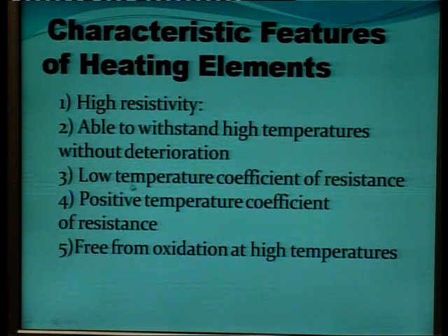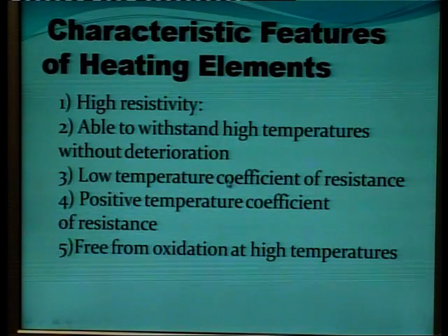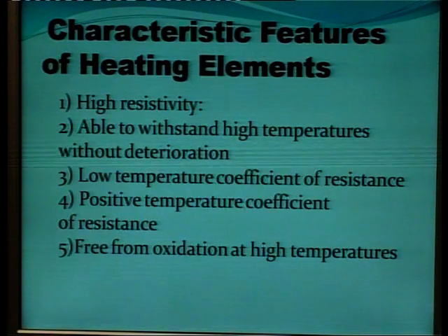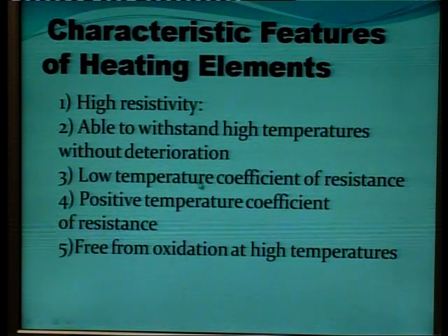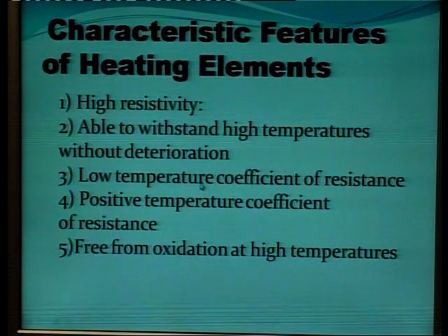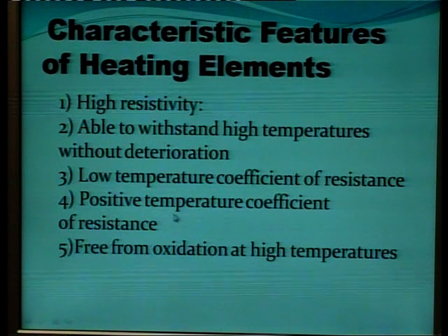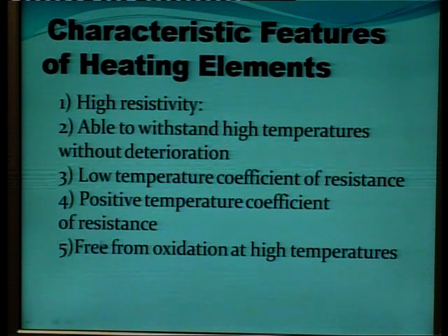Third is low temperature coefficient of resistance, meaning resistance must not vary with the variation in temperature. Otherwise it would have a high starting current. Fourth is positive temperature coefficient of resistance, and fifth is it must be free from oxidation at high temperatures.